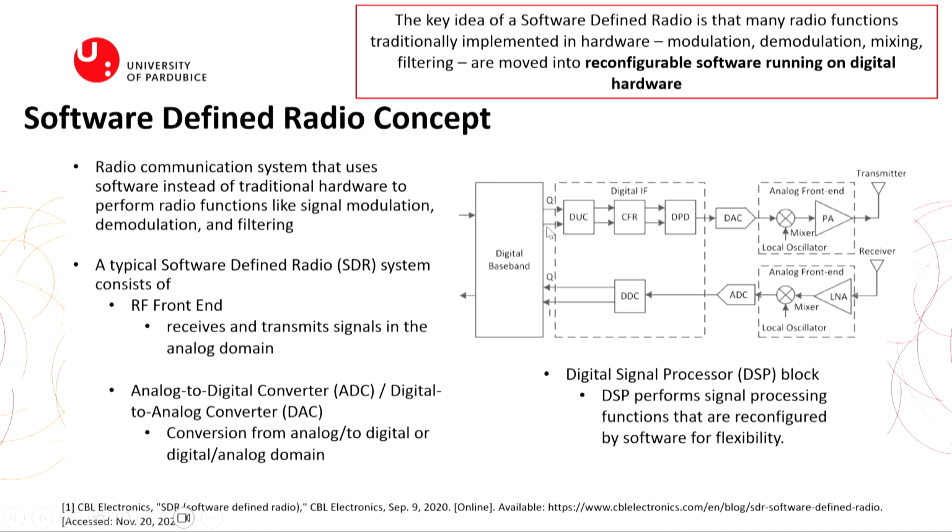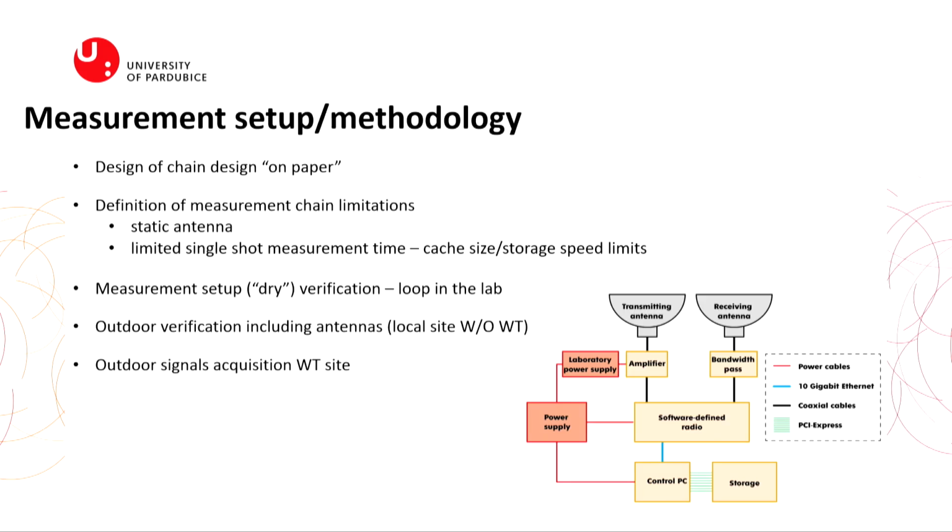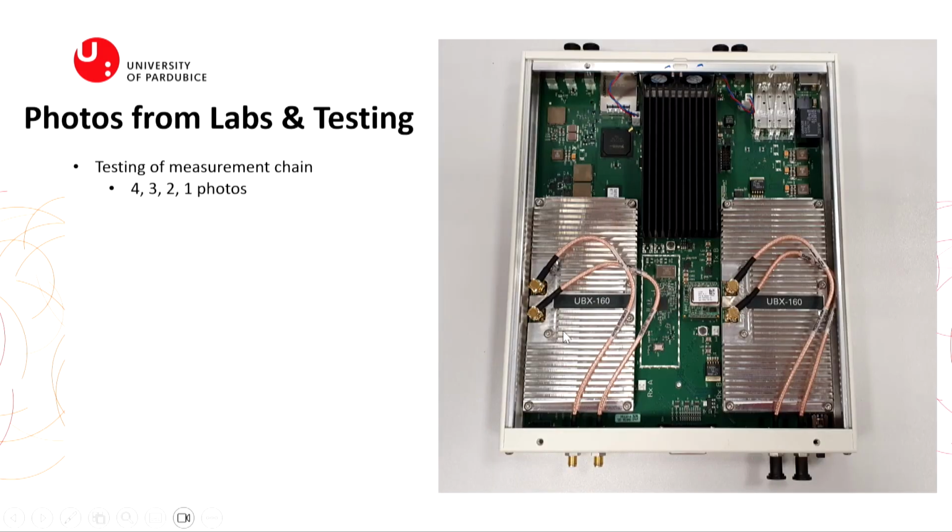And of course there is IQ data, the digital baseband, and there you can continue with modulator software processing, whatever you want. It depends on the signal that you are recording. It completely corresponds to these two analog parts, and the rest is just digital. It is FPGA. Again, it is just data.